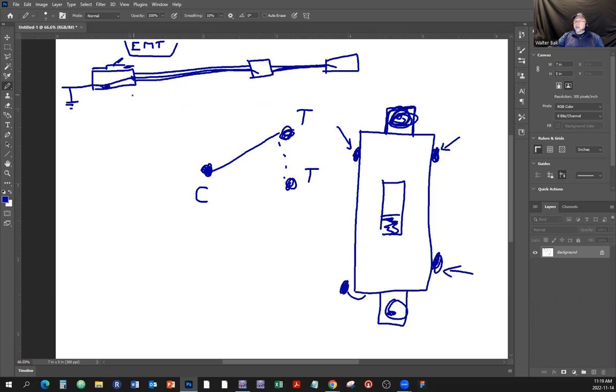All right, if you have PVC tubing, then of course you're going to have to run a grounding conductor, which would be green or bare copper. Well, it's going to be green jacketed if it's in tubing, and then you're going to have to connect all the bonding terminals to the bonding terminals on the boxes, and from that, this bonding terminal has to be connected to the bonding terminal on the box. So that's if it's PVC plastic, okay?